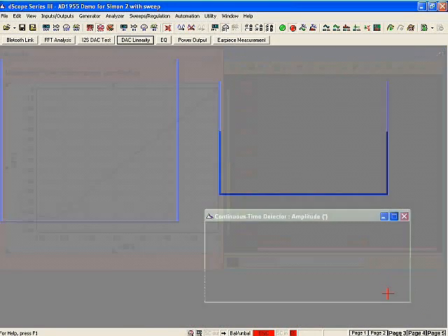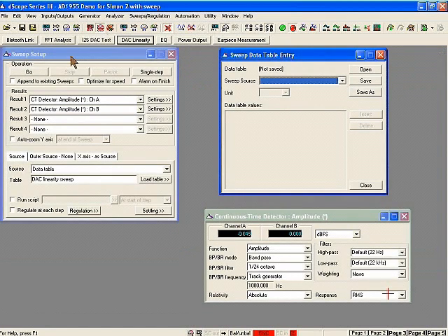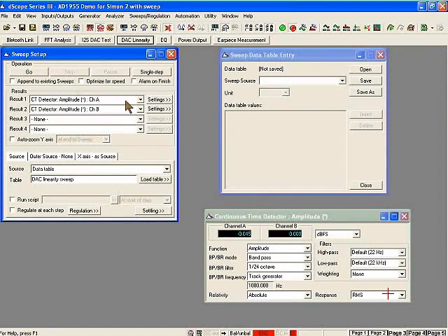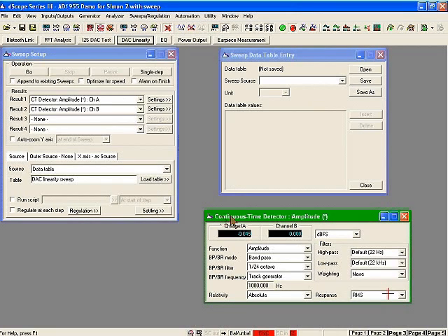So in order to recreate that test, I have set up a sweep in the Dscope software here. And in this example, because I'm going to be measuring a signal that will be approaching the noise floor down towards the lower end of that curve that we just saw, I'm using a bandpass filter response, which will restrict my analysis to a very narrow 1/24th octave band centered around the frequency that is configured in our signal generator. And that will enable me to measure this signal down to very low levels in the presence of noise and get a reliable result.